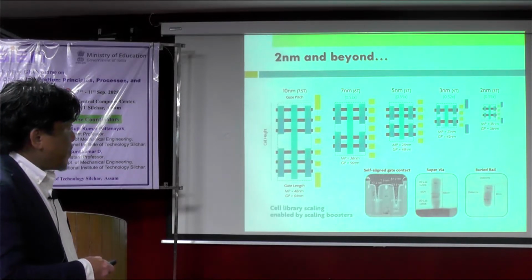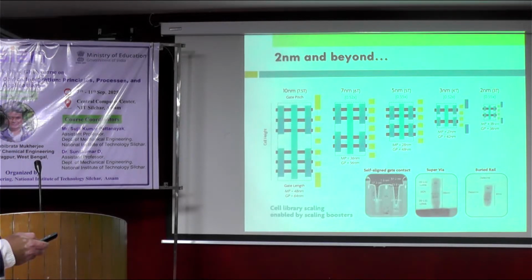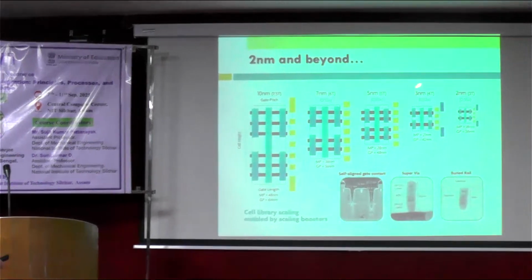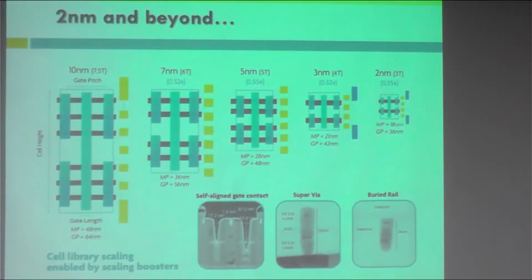Okay, but the next thing that we have to think about is the materials. Let's say now we are talking about 2 nano. I mean, previously 3 nano line size. So it's not just about a difficulty in terms of fabrication process. But we need to think of when it goes to 2 nano, what will happen to the resistivity of the materials?